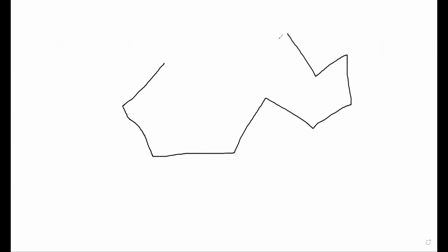So when you have a polygon, let's say this is your polygon. It can be of any shape with any number of sides, it doesn't matter. You have one line with a bearing. Let's say you have measured the bearing of this line. Let's say this is north, and this is the bearing. We have to consider everything in anti-clockwise direction.